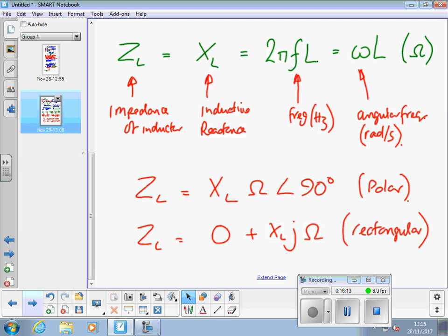What you must bear in mind here is it's absolutely impossible to have a circuit with pure inductance, because an inductor is essentially a coil of wire like a motor or a transformer winding, and therefore that conductor has some resistance. It's not possible to have a purely inductive circuit, but theoretically if you could have one, you'd get exactly 90 degrees phase shift. Current would lag by 90 degrees.